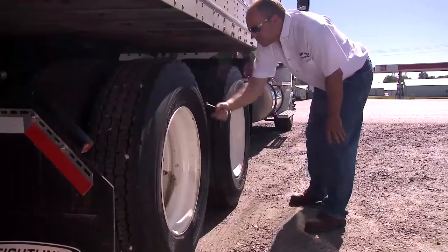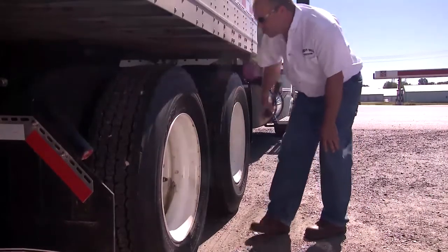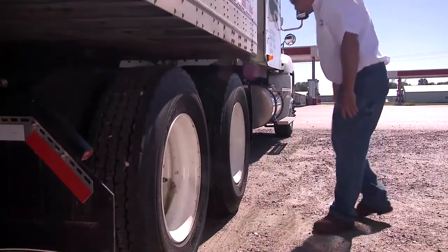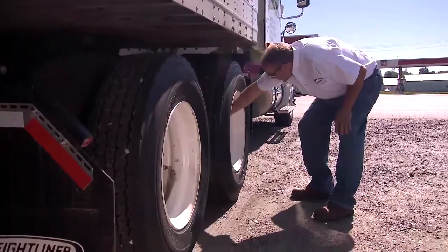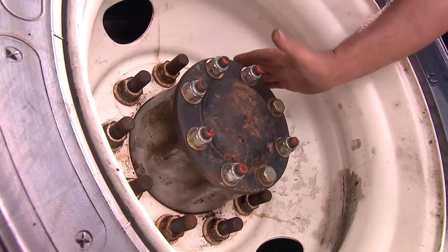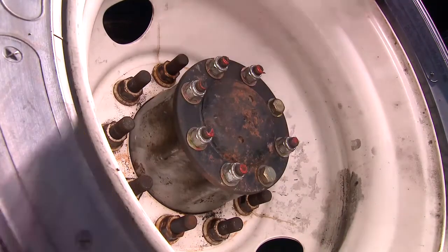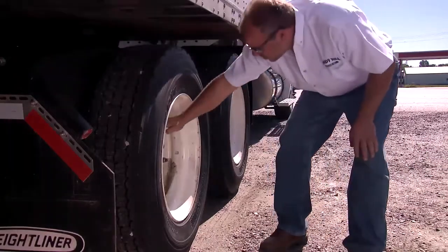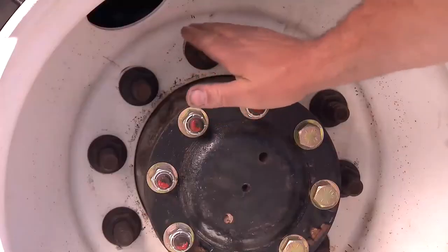It won't do you any good to use an actual pressure gauge to test your tires when they're hot, since a reading can be off anywhere from 5 to 20%. Instead, use a hammer or tire thumper to check for firmness. Also, put your hand close to the hub and feel for excessive heat caused by a failing tire or bearing. But be careful not to touch anything. You don't want to burn your hand in the process.